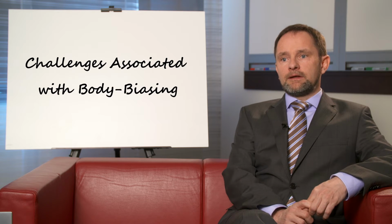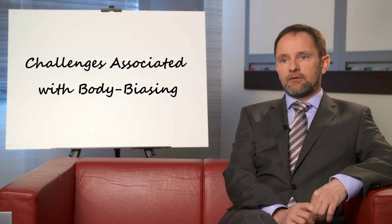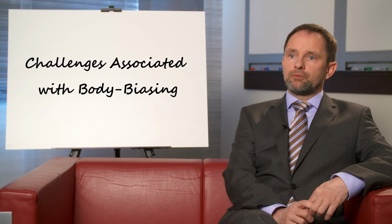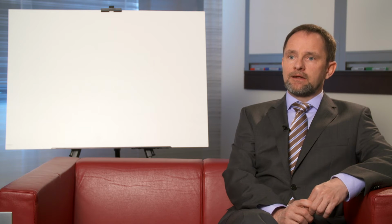The body biasing brings new challenges to the design implementation area. The design team needs to take care of the different cell libraries. They need to define them in the UPF IEEE 1801-2009 file to be able to have proper connections in the design and to place the cells correctly. In addition to that, with applying bias voltage and bias routing in that technology, it's required to apply high voltage rules to the bias network to protect the bias network and the adjacent cell routing.